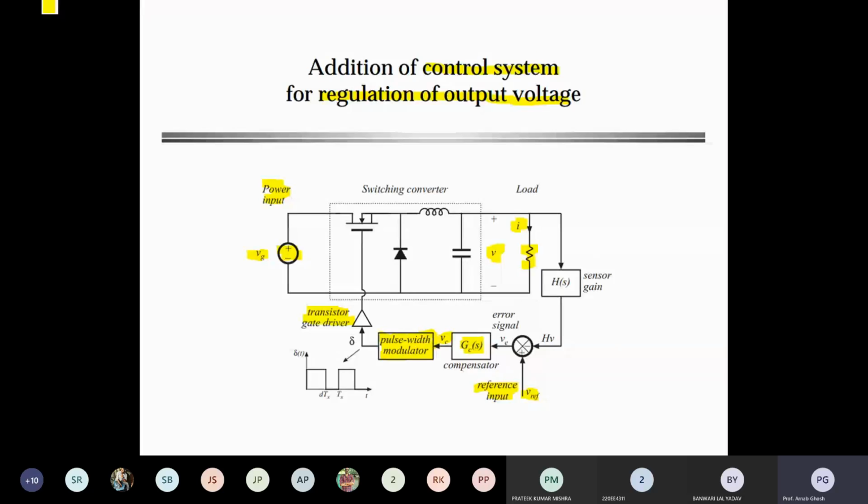So you can understand, for the line regulation, the unit is per input voltage, so again the unit is 1 by V. But in case of load regulation, it is unitless. But again in case of temperature regulation, it has a unit, that is per degree centigrade. Many power supply manufacturers specify only an overall percentage of regulation together with the limits of input voltage, output current and temperature. So the regulation is V max minus V min, whole divided by V nominal, into 100%. I think all of you are able to understand.